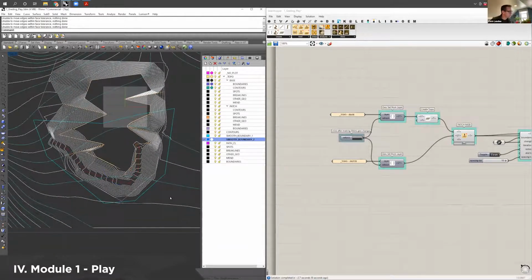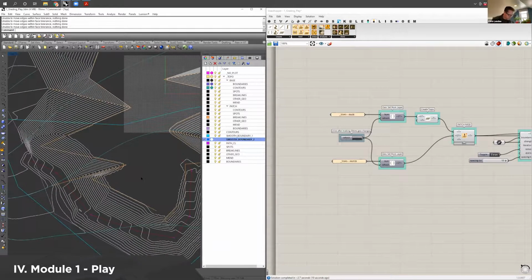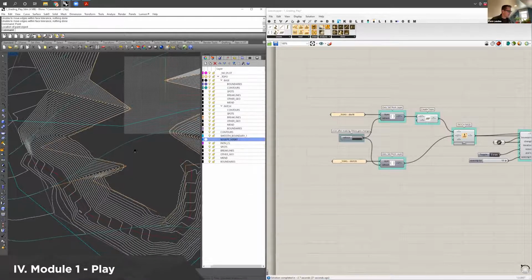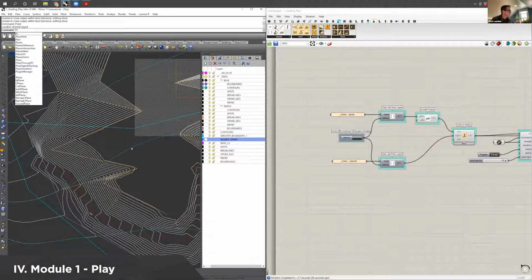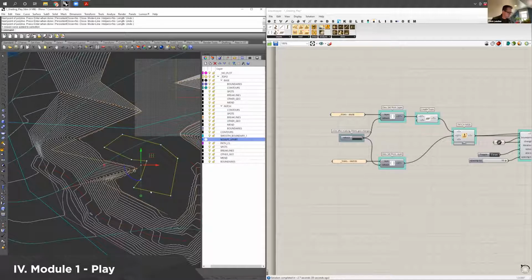So if I want, say, a feature once we get down into this valley, I'm going to draw a bunch of points. Just rename this Sculpt stuff. And I want a basic platform, so I'm going to draw a polyline. And I want this platform to be here. And I'll just do PS to do a planar surface.